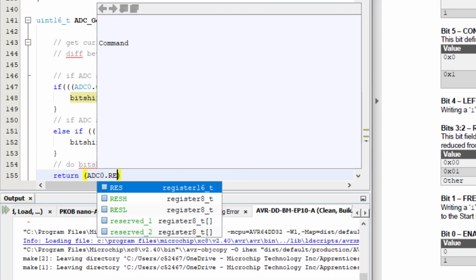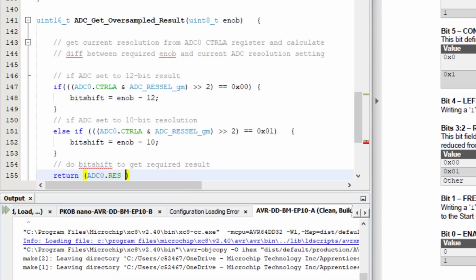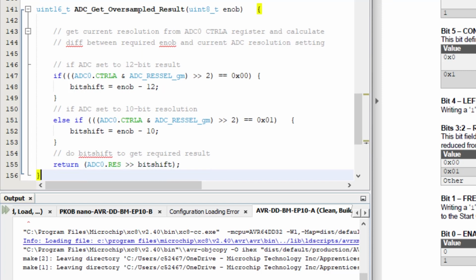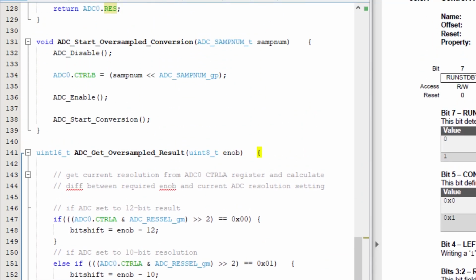We're almost done. We need to keep in mind that since we have set the window thresholds, we may need to adjust them since the window compare works on the accumulated value and not the decimation that we have just done. However, I will leave them as they are.